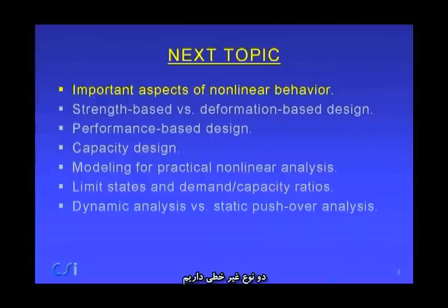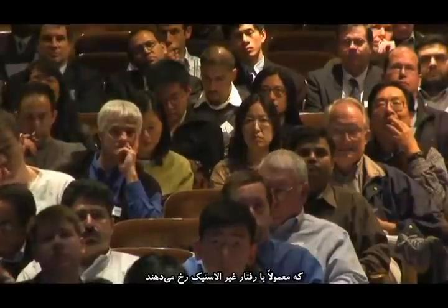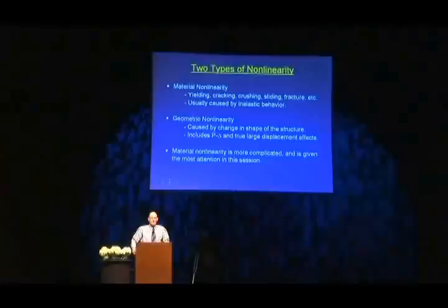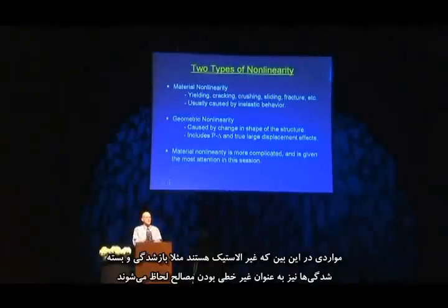There are two types of nonlinearity: material nonlinearity, which involves yielding, cracking, crushing, sliding, fracture, and a number of other things. And this is usually caused by inelastic behavior. But such things as gap opening and closing, which are not inelastic, are also regarded as material nonlinearity.